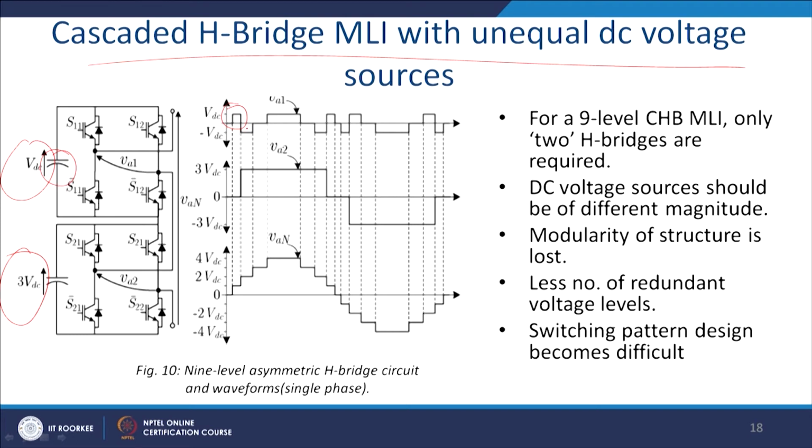So, you see how you generate different levels with just the 8 switches. That is the beauty of this unequal DC voltage, but it has to be separate. So, you give a negative, you get a positive, you give a negative, you get a positive, and thus you generate this square wave. So, what should be the level of the voltage, and thus you get a multi-level, multi-step inverter. That optimization is also a great scope of research, and you find plenty of research papers on it.